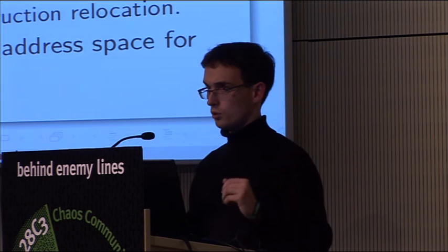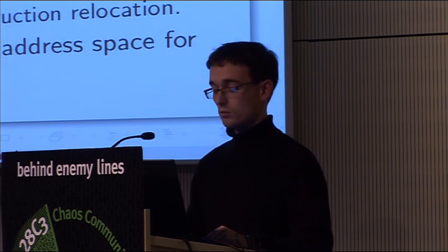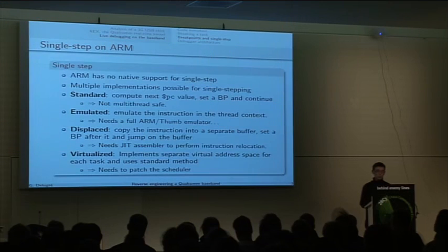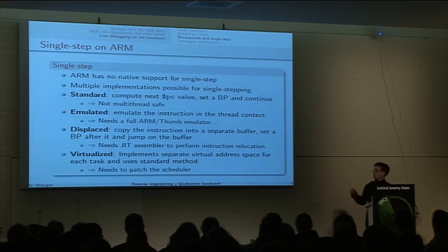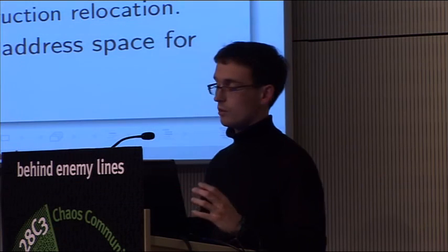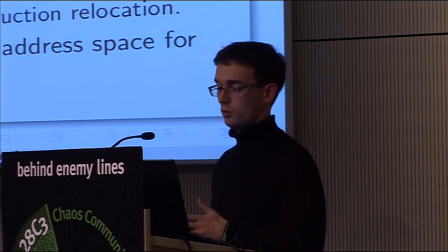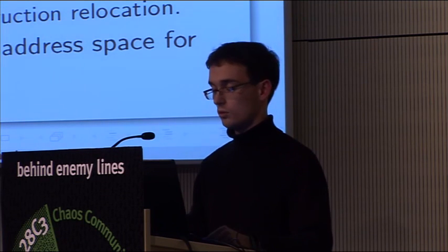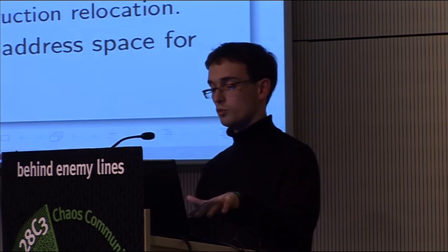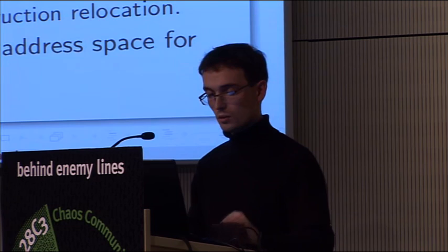If you want something which supports ARM and Thumb, another solution would be to virtualize the address space for each task. In this way, you just put a breakpoint, use copy on write for the page where you put the breakpoint, and in this way, other tasks are safe for execution. But for this, you need to patch the scheduler and implement page tables for each task, and it's quite painful too. So, well, my solution for the moment is to use a displaced breakpoint and standard tools.